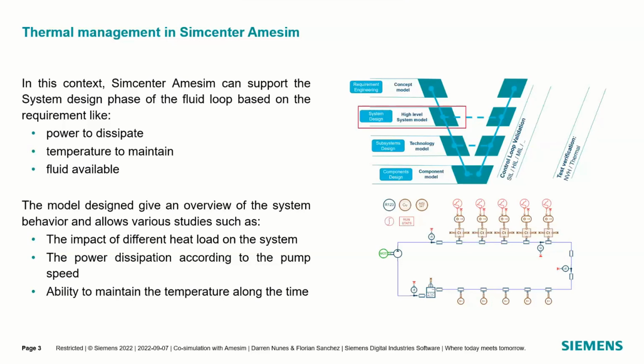We have different signals that we send in that are different heat fluxes, and we get temperature readings out of them. But ultimately, we're looking at a pump that is sending a refrigerant and seeing that heat exchange and dissipation across it. In that model, we have a pump. On the bottom, we have an accumulator, and we have different sections of the pipe that we can get sensor readings off of, that ultimately you can use when you do this level of co-simulation within the tool sets.